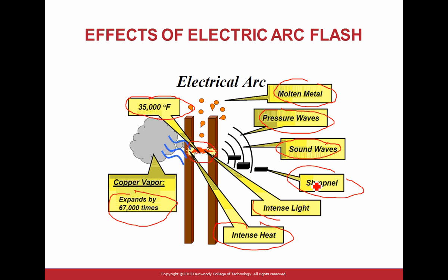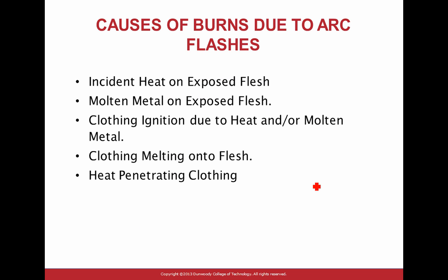That's why, guys, OSHA and the rule, I want to remind you, the rule is de-energize. Especially if you're working on power, the rule is de-energize, if you can. Is that outfit fire resistant too? Yes, arc resistant, they call them now. After 2011, they changed from fire resistant gear to arc resistant because arc encompasses the fire and the arc.